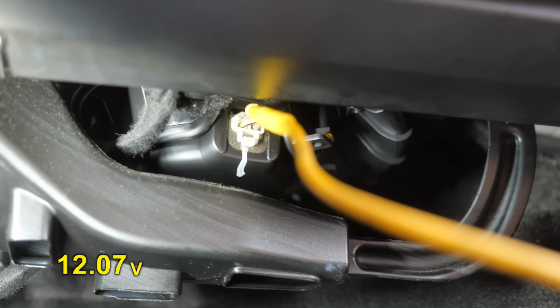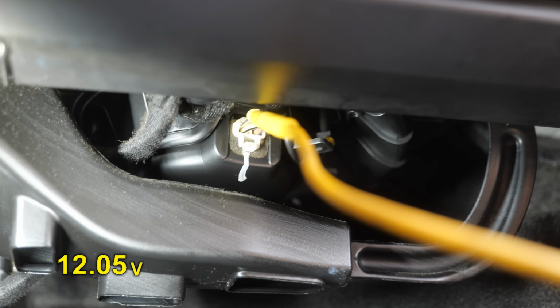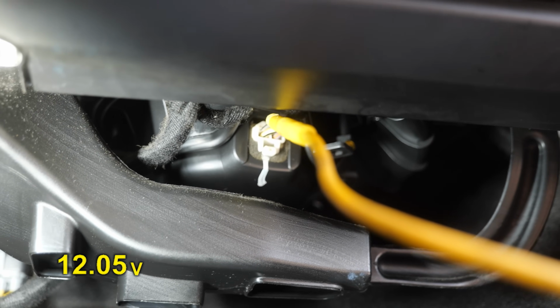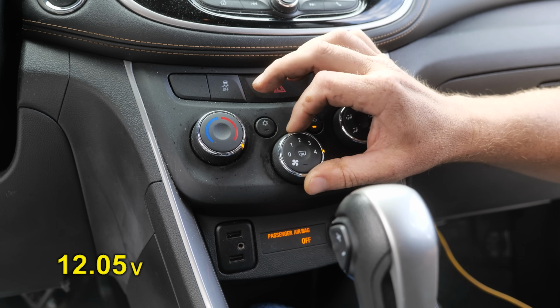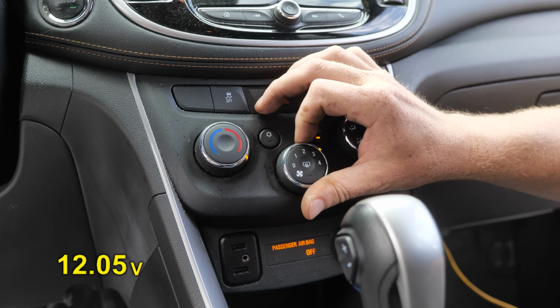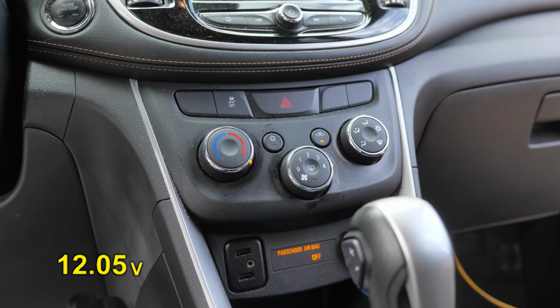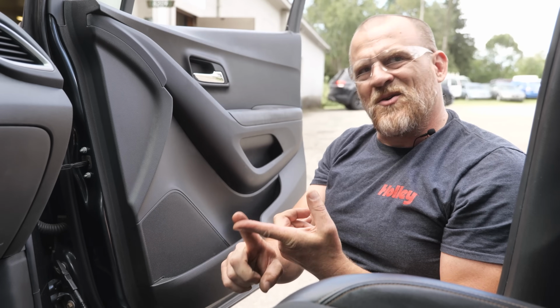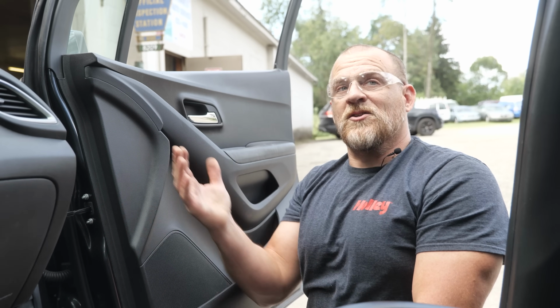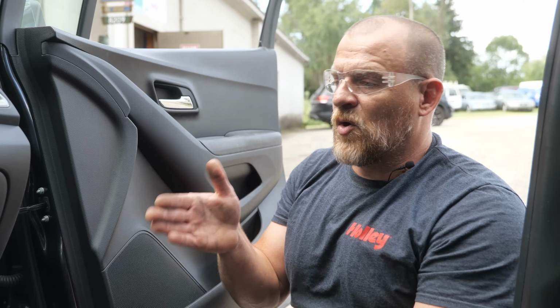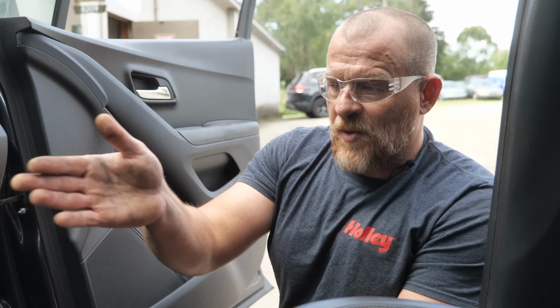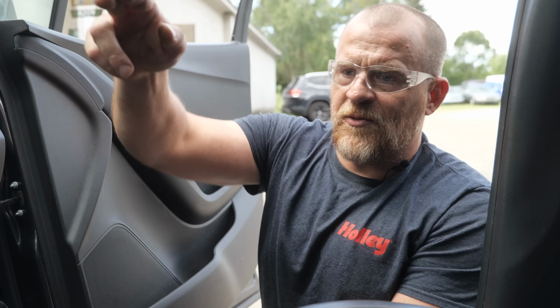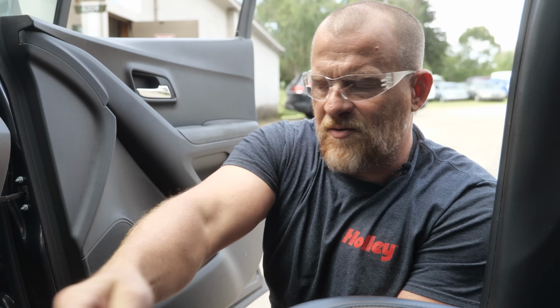That's the other wire. So what that's telling me is there's no ground for this right now. And up here on the switch now, no changes. What we do know though, by the 12 volts to the blower, is we know the BCM is sending its signal to the relay. We know the relay is turning on, and we're sending voltage down to this blower motor. So that much we know, but I'm missing a ground. The ground is controlled through the blower motor resistor, and then through the switch, and then to a ground that's under the center console.